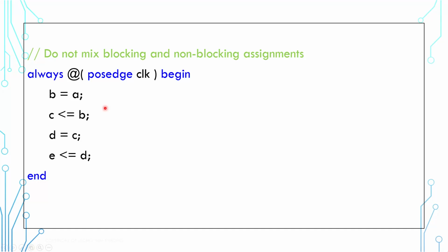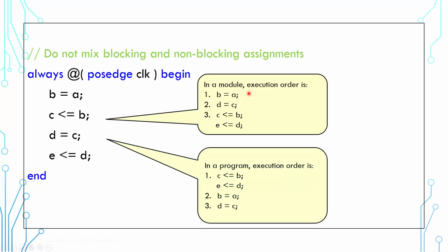Now before we stop, please do not mix blocking and non-blocking assignments. If you come across it, you should know the behavior is different depending on if the code is in the module or if it is in the program. Please refer to the scheduling semantics video.